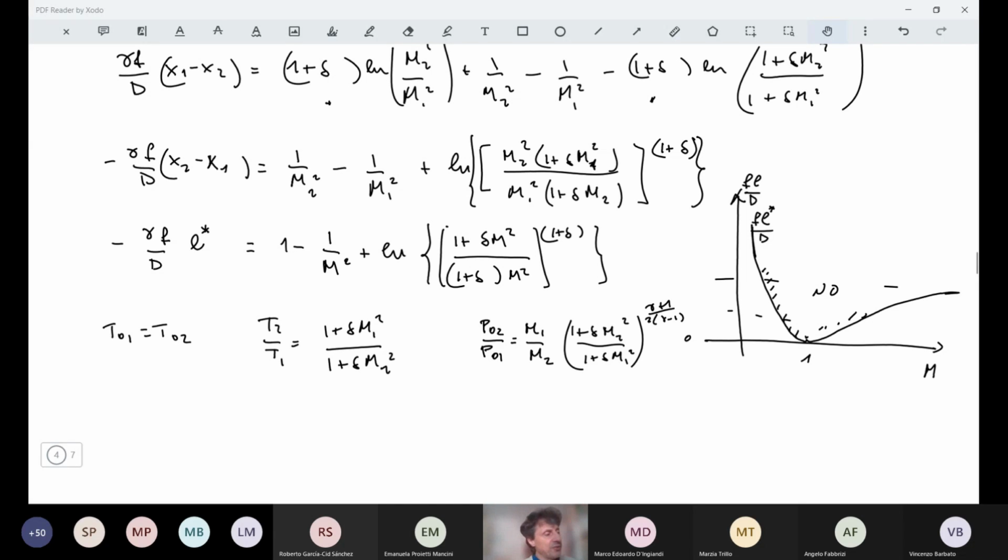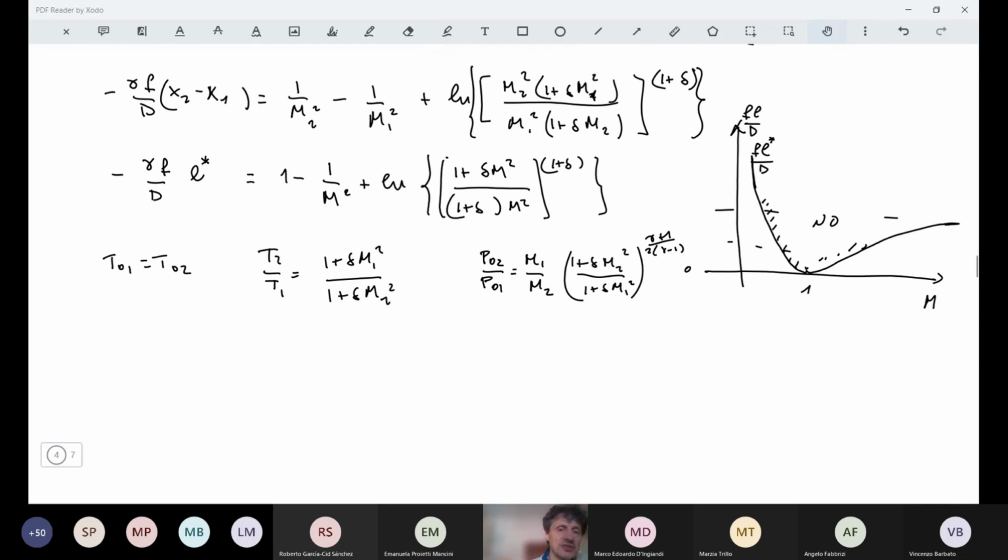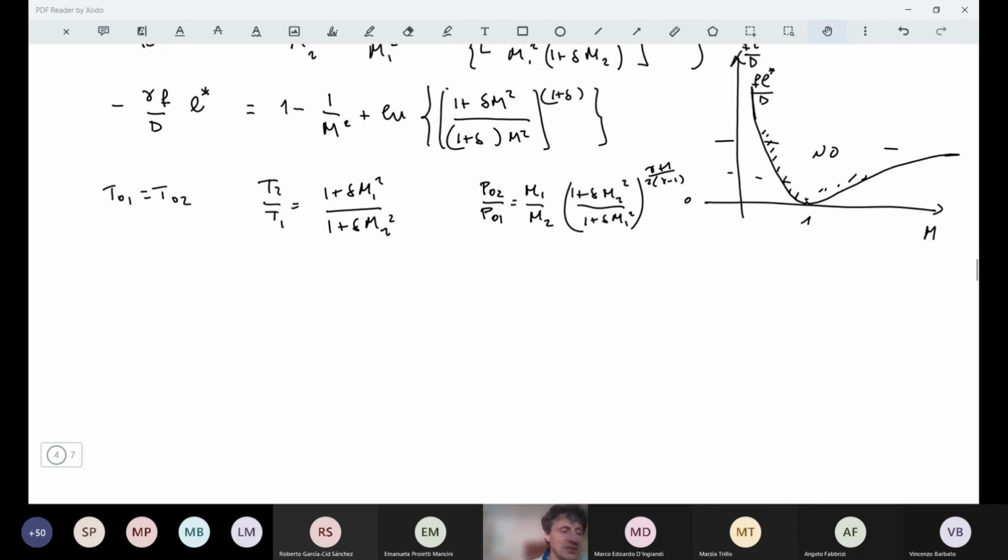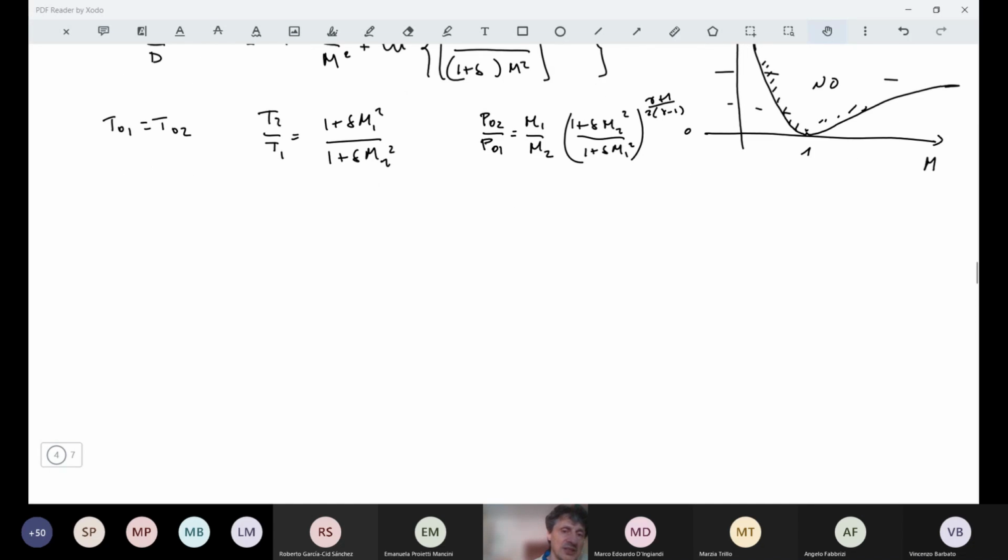The behavior that we have of the flow with friction that we have analyzed here, starting from the governing differential equation, is also seen in terms of the integrated values. And in particular, it's of interest to see the locus of points followed by a flow with friction in a temperature entropy or enthalpy entropy diagram. Let's consider our TS diagram, and that we have a given point on this diagram, which is our inlet conditions, our value 1.